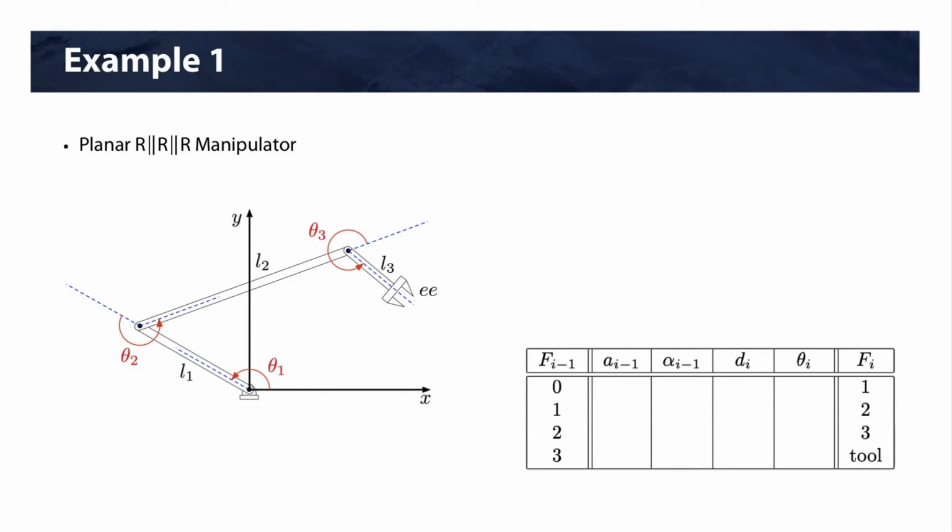Now, the first step in solving these problems is to draw a zero displacement diagram. And remember, a zero displacement diagram means what does the robot look like if all the joint values are 0. This shouldn't be confused with what is sometimes referred to as the home configuration of a robot. The home configuration can be any joint angles you set. But in zero displacement, all our values are 0, and it's how we assign our D&H parameters.